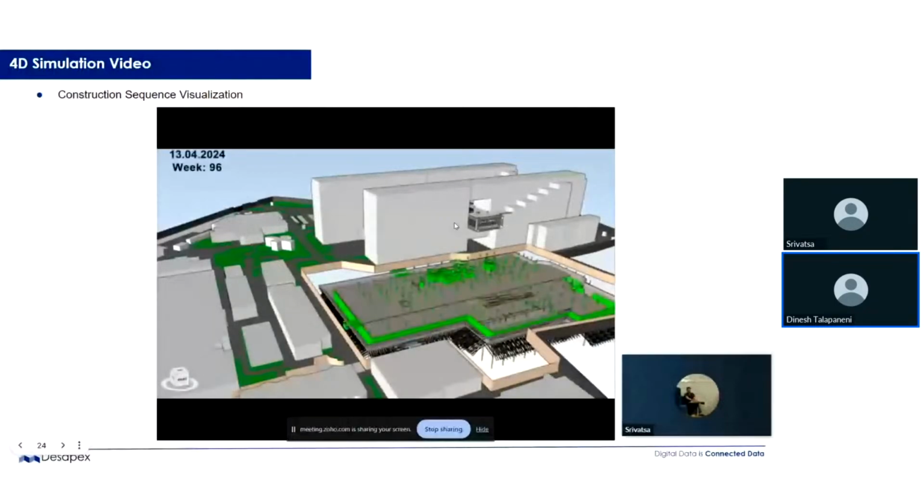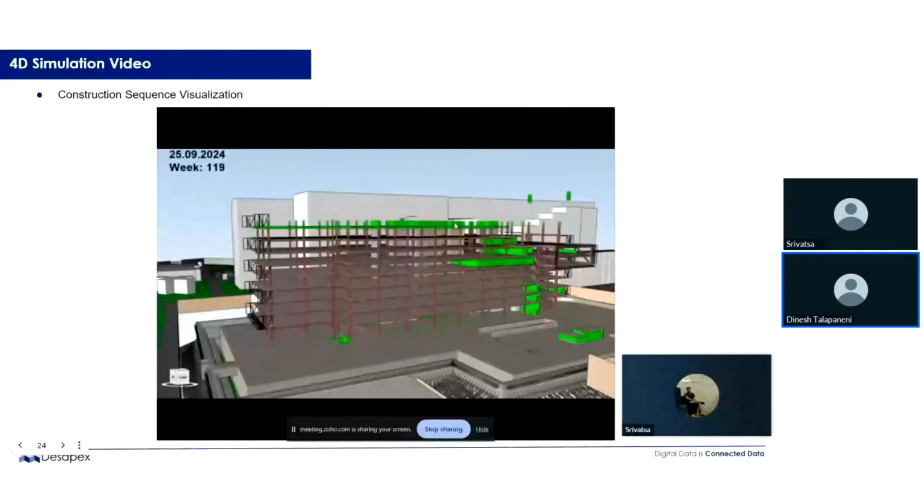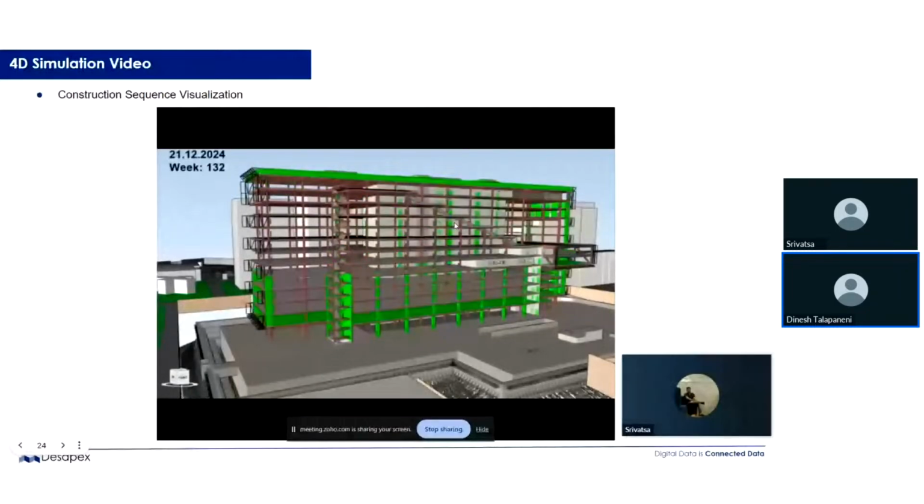because when the contractor is on board, the schedule goes to one more minor level where you break the schedule into execution based on the pours, like I was talking about the slab. So we bring in a lot of activities into it, and similarly break the floor into pours, assign WBS IDs to those, and then have one more virtual construction simulation at the construction stage. This one is just to understand how things have been planned and modeled until the detailed design phase. So basically, you have to do this activity in the construction stage as well.